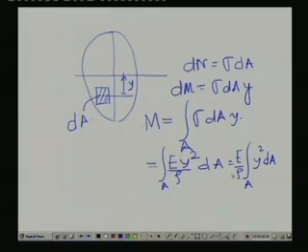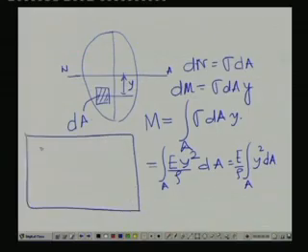So, what do we get? The total moment, once again you can recognize this term, the integration over the area y square dA. This is nothing but the second moment of area about this neutral axis. Okay. So, we get an important relation from this, that is M equals E I by rho.